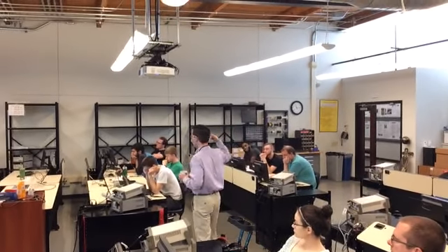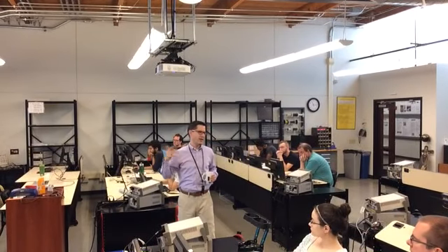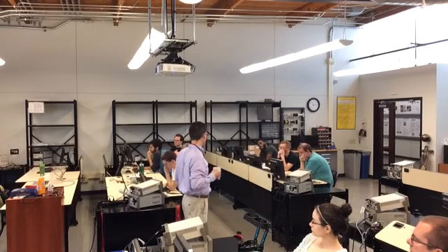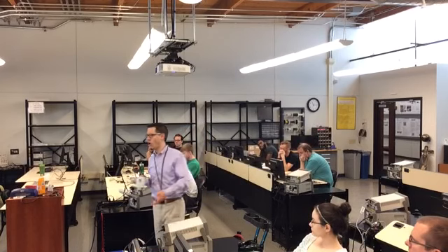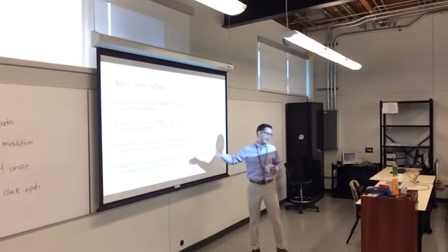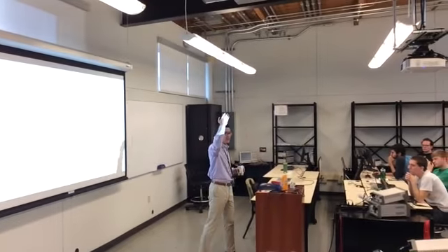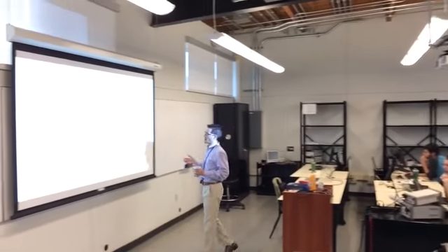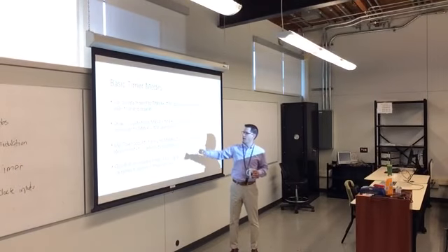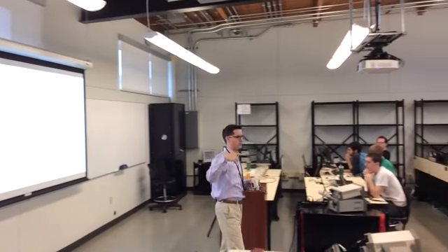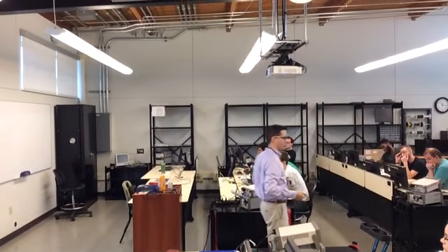This is always going to be unsigned math. There's no point to have a signed value in a timer. So if you've got 8 bits, then you have 2 to the 8 minus 1 values that you can count. Some other modes are up, down. This is where the timer goes up to a limit and then back down, and up to a limit and then back down. So it just oscillates between 2 fixed values. Well, it oscillates between the top value and 0. So when it hits the top value and turns around, you get an overflow event. When it hits the bottom value and turns around, you get an underflow event.